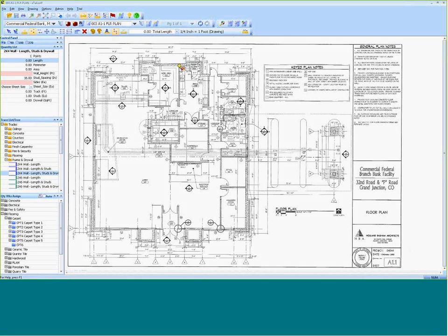Okay, so let's go measure the wall again, same wall. I'll measure it, lose track of that, but now I can go say, okay, the wall height, let's say a 12-foot high wall, and instead of spacing is 16 inches on center, I want to put drywall on both sides of that wall, and I want to use drywall sheets that are 4x8. And the results I get all the track, stuff, drywall, and how many sheets it is. Feet. So a lot of great information can come out of one of these extensions.